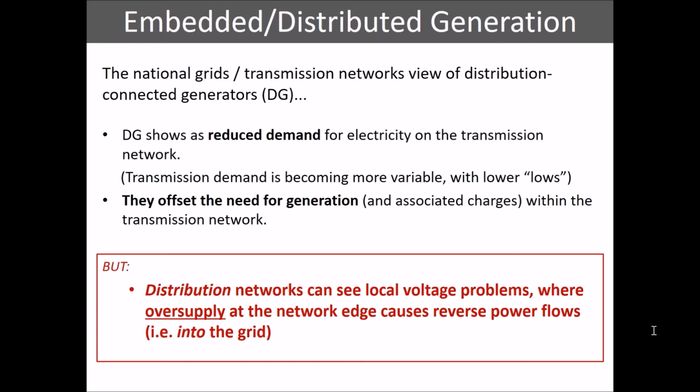And there are various ways around that. You can upgrade distribution lines, but that's pretty expensive. Or we can look at things like storage. It makes obviously logical sense to store that solar energy when nobody's there to use it and then deliver it back out of a battery when they get home. Not only does that seem logical, but it also helps mitigate some of these issues and reduce some cost in the distribution network. So we've seen these kinds of problems in markets like Germany, also markets like Hawaii, for example.